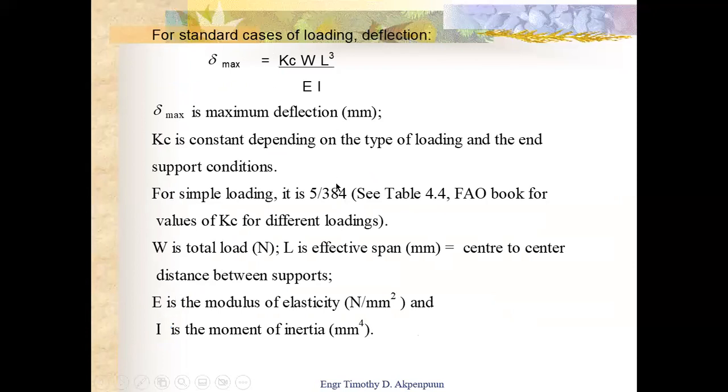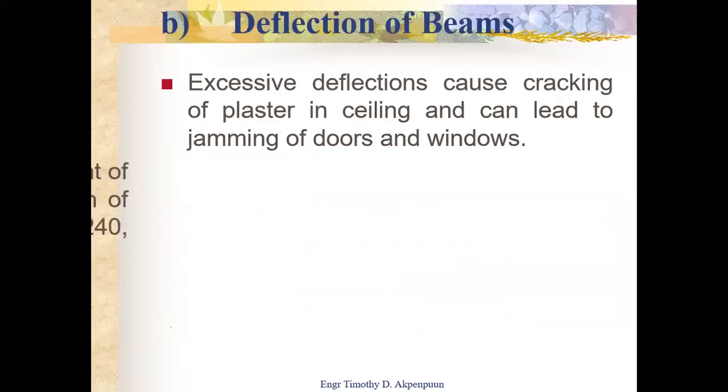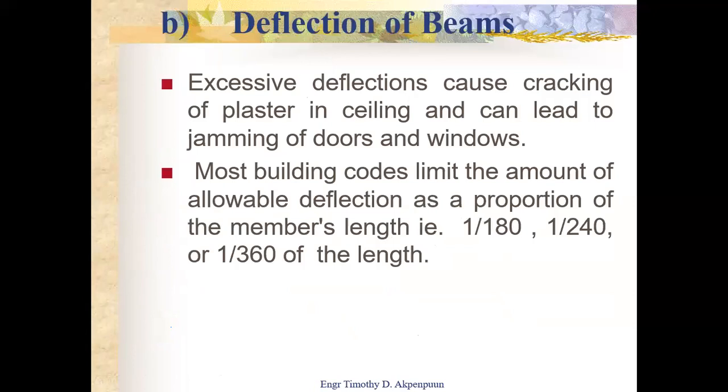But you guys should forget about this equation, it's too complex. There's a simpler one. So these are the allowables. And for your design to be correct and to be safe, your allowable deflection must be greater than your calculated deflection. Understood? Yes, sir. And as well, your allowable stress must be greater than your calculated stress.